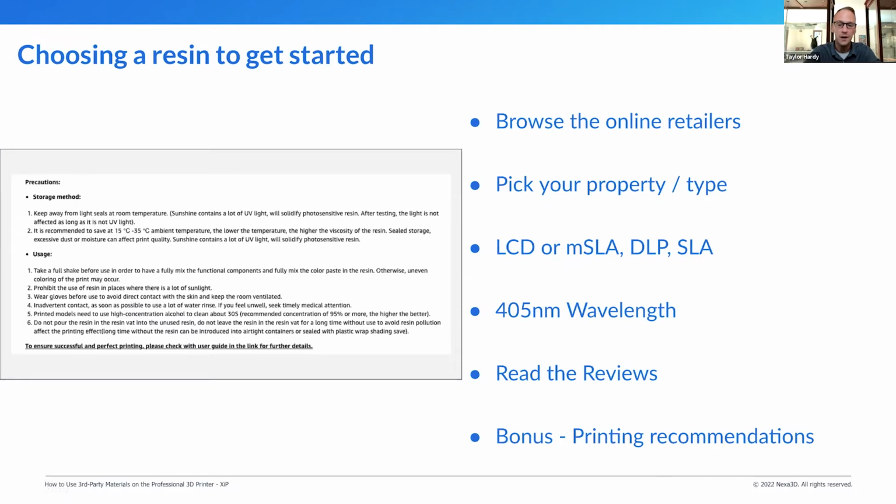So yeah, of course, I think I mentioned this before, there's always going to be printing recommendations. You want to make sure you're not near a window. You want to make sure you're storing your resins correctly at the right temperature. You always want to give it a good shake before you load it into the platform, and make sure you're using proper PPE. So it's pretty standard for anybody that's used an MSLA printer before, anybody that's printed with resin in general.